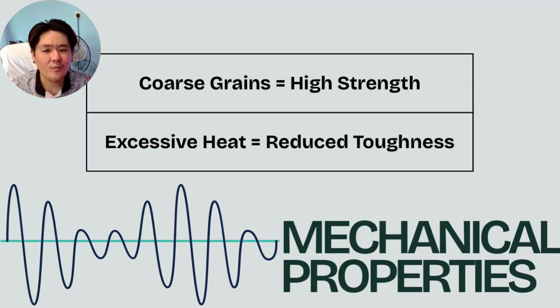What does excessive heat input during welding or heat treatment cause? It causes grain growth, the loss of fine microstructure, and also reduced mechanical performance, because when the grains become too large, the material loses its toughness, meaning it becomes more likely to crack or fracture suddenly. Brittleness.